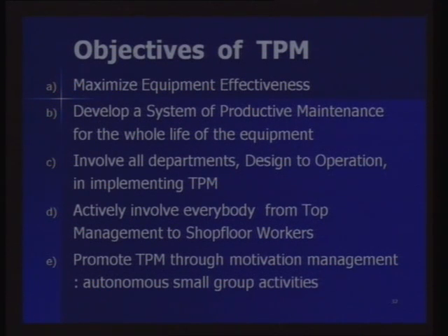Involve all departments, from design to operation, in implementing TPM. The term total means the participation of everybody in these activities. So design to operation, those people should be involved. Actively involve everybody from top management to shop floor workers. Promote TPM through motivation management, that is, autonomous small group activities. Actually Japan has developed these autonomous small group activities in a big way from the 70s onwards, in every field, whether quality, maintenance, or any type of manufacturing, and their success is known to everybody.